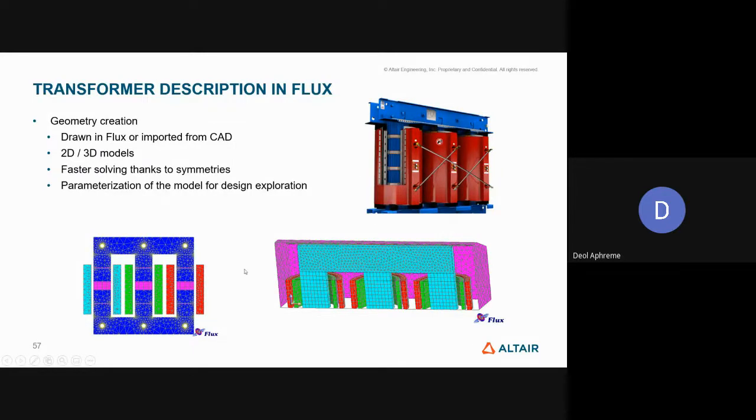This is a very realistic design of a transformer, so that we do not have a complete magnetic circuit. Shorting them would be like inviting trouble, so we do not usually short them completely. There is an air gap of some sort between these regions, or laminated regions.